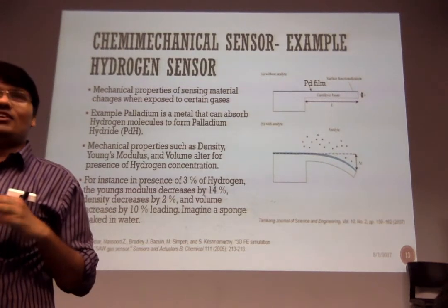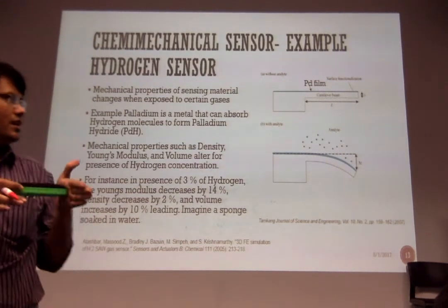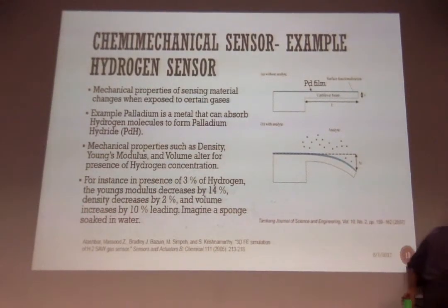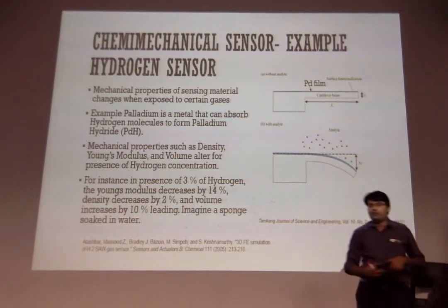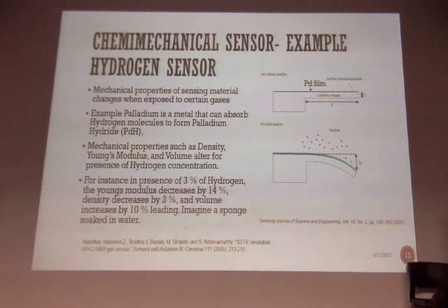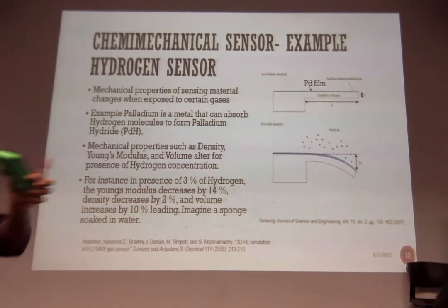Okay. So what happens is, when I coat this palladium on a cantilever, say it's made of a silicon microstructure, and this is a palladium film. Now, the fundamental frequency of this structure, say it is some X hertz. Now, upon absorption of gas, the mass is changing.